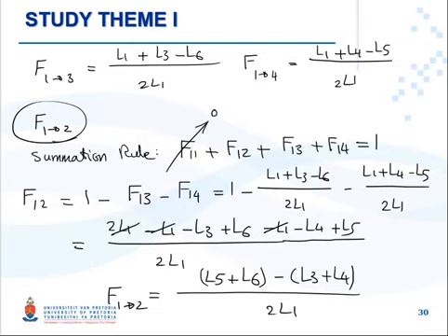But of course, using tables and standard geometry can help a lot, but you can't just use those tables and figures to find the view factors. You always need to incorporate the self-view factor as well as the rules that I told you about: either reciprocity, summation, superposition, or symmetry. Okay, now let's finish this section with an example.